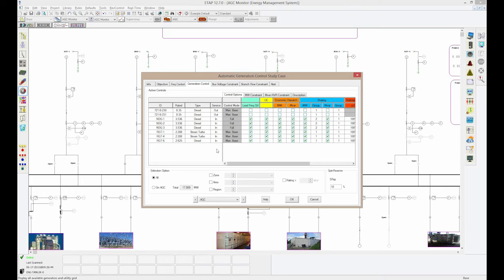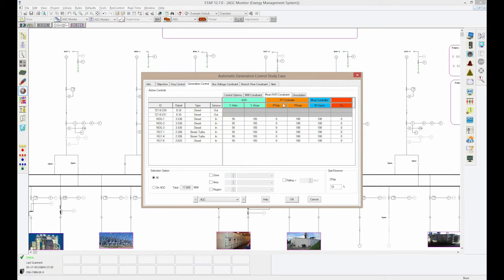And then we have different generators, obviously, in the system that I'm utilizing in addition to any of the renewable sources. Only the conventional generators are shown here because they are the only ones that are easily controllable. Even though you can technically apply some sort of control to the inverters and manage some level of voltage control from the renewable sources, the focus of the generation control here is megawatt, and then the secondary objective is reactive power or voltage. So you can also set up the voltage regulator and the power factor controller here.